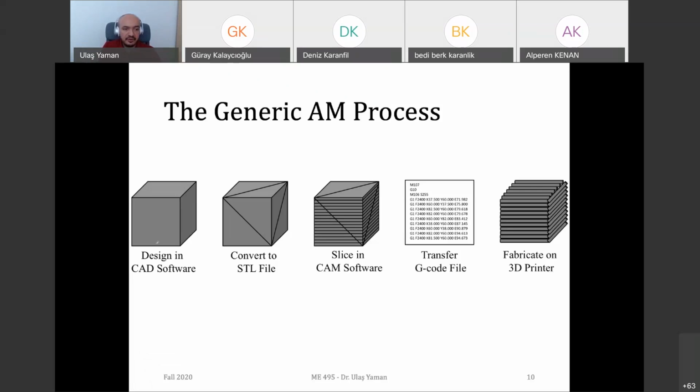Yes. So in the next step, we simply do a triangulation. This is a very simple one. I will divide these square surfaces into triangles. And you see in the second step, we represent this cube by using how many triangles? We have 6 surfaces, and 2 is fine for a single square surface. So we have just 12 triangles in this conversion.